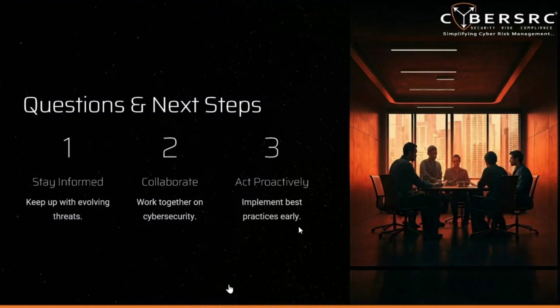Machine learning and AI. What role do machine learning and AI tools play in modern OT threat detection? So basically, let me take a real world implementation. We can implement a SIEM solution to gather all the data, or a network based intrusion detection, so basically gather all the data regarding the network or any kind of intrusion, and then pass it through an AI to analyze it and be ready to take a preemptive response.